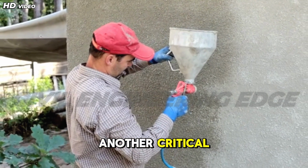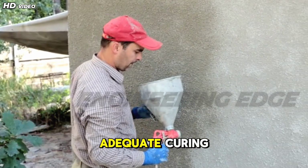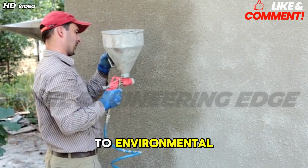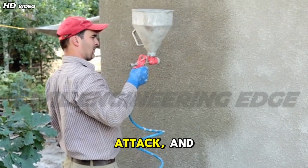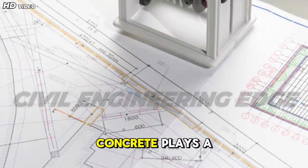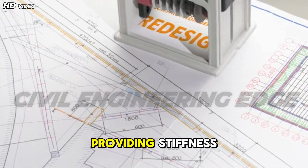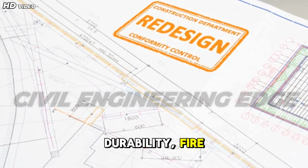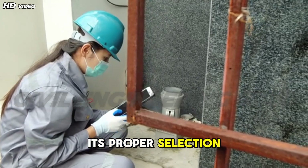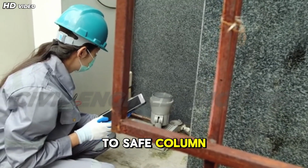Durability is another critical property of concrete. Proper mix design, adequate curing, and suitable cover ensure resistance to environmental exposure, chemical attack, and long-term deterioration. In summary, concrete plays a dominant role in resisting compressive forces, providing stiffness, durability, fire resistance, and protection to reinforcement. Its proper selection and quality control are fundamental to safe column performance.